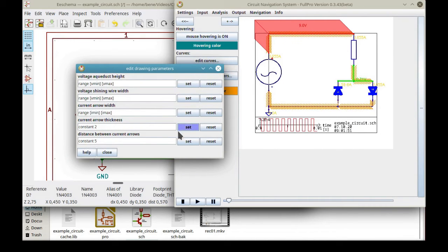But now they are so close to each other, a little distancing would be good. Also, let's edit the range of the voltage arrows to display the range from -5 to +5 volt. Everything below or above this will be cut off.